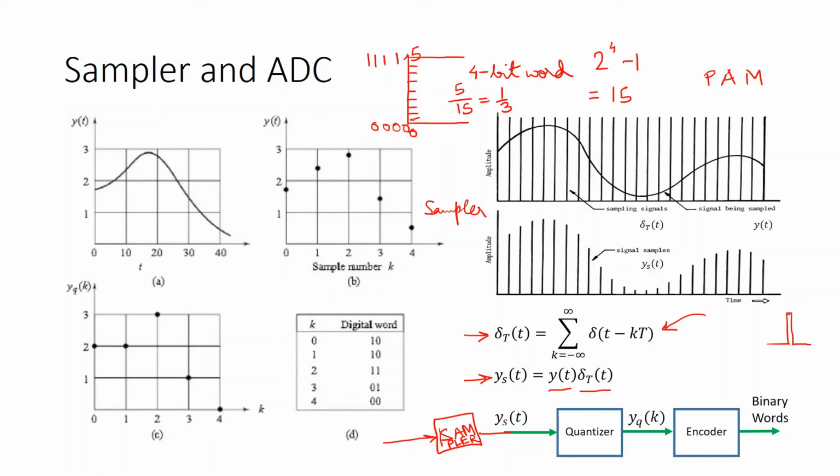So what is the point here? The point is that you cannot have any arbitrary value being fitted by a binary word. So what to do? We have to quantize the analog value. Quantization of the analog value means to shift it to the nearest binary level. Suppose you have a value of 4.9. You cannot have 4.9 here, so you shift it to 5 and get the binary word 1111. Similarly, 1/3 is basically 0.33.